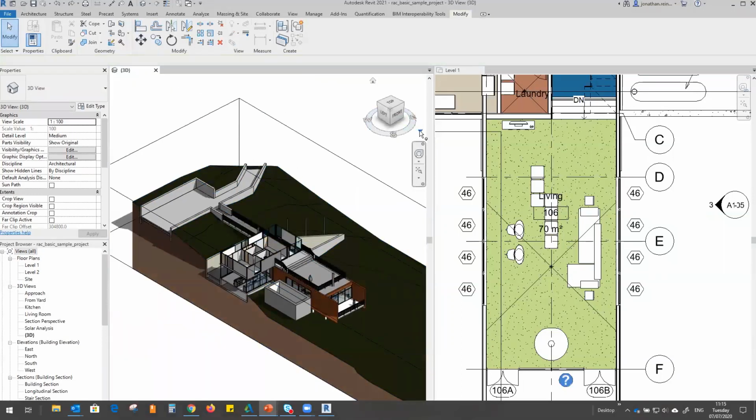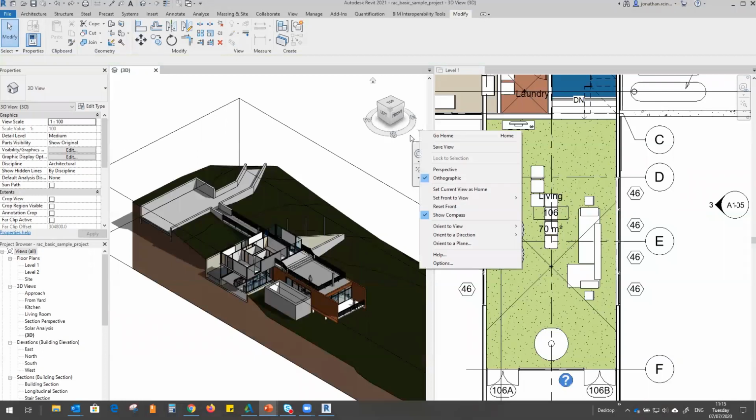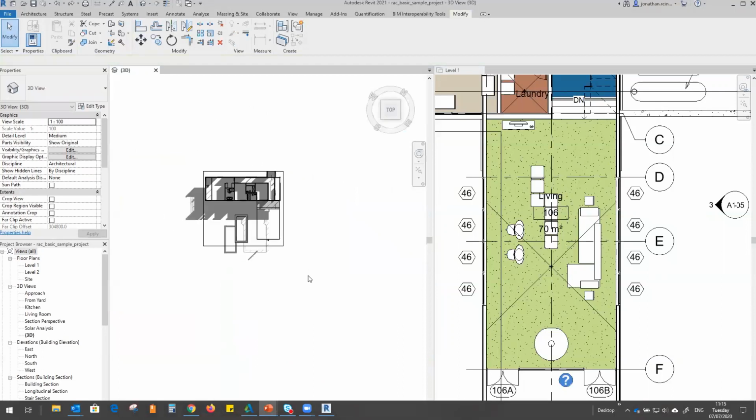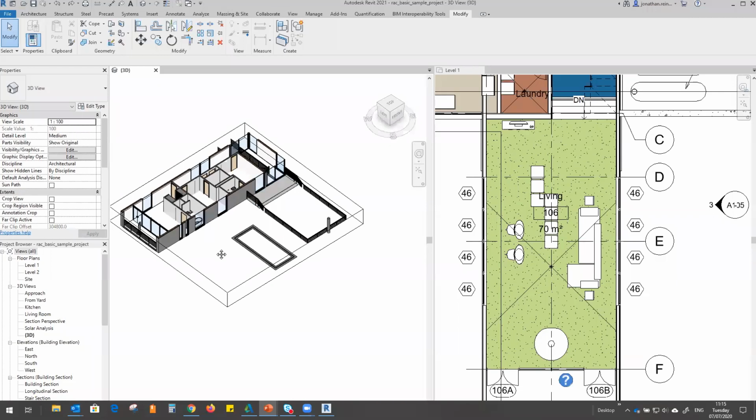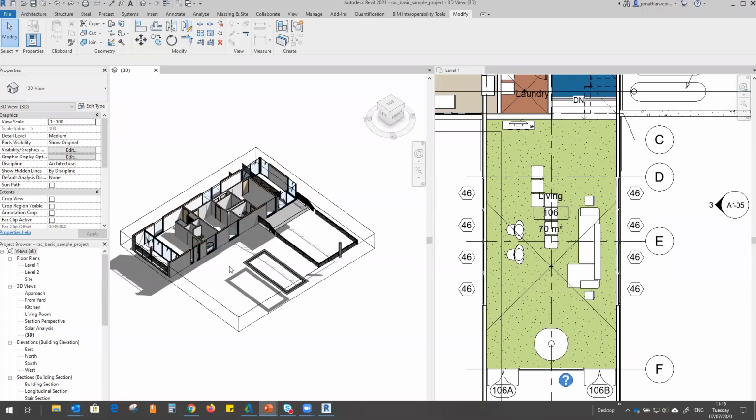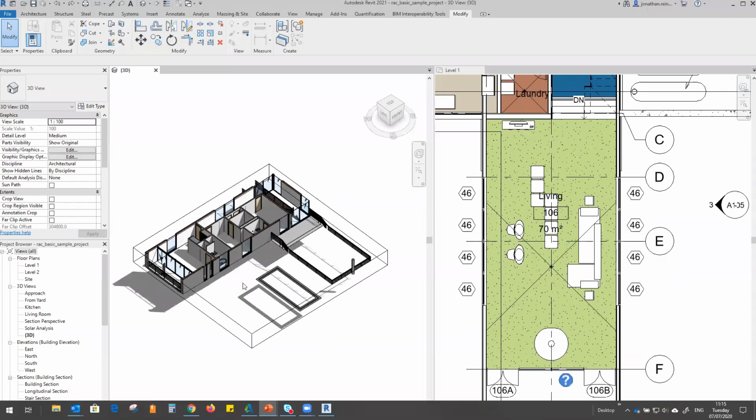And another very handy tool as well is if you go to your View tab here, and if you want to create a 3D view, I can go to any one of my particular views, floor plan. I'm going to go to floor plan level 2. I'm just going to right click on this, and all this is going to do is rotate me to that particular plan view, and it's going to hide everything else other than what is located at that particular level.